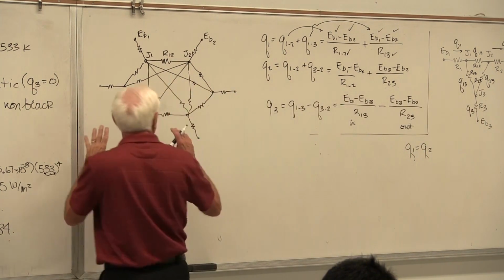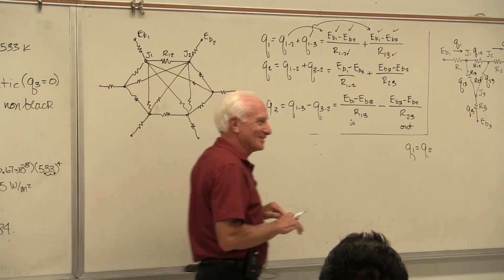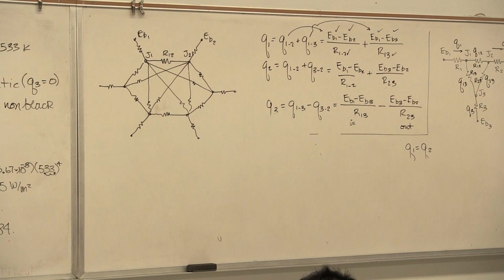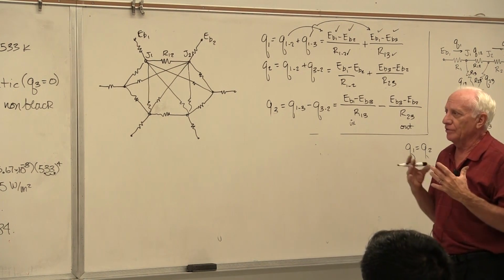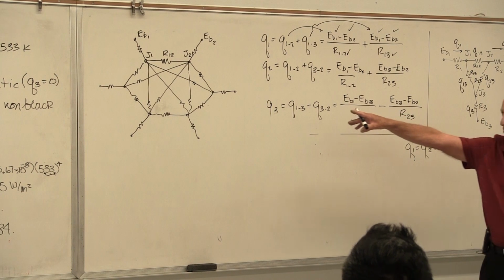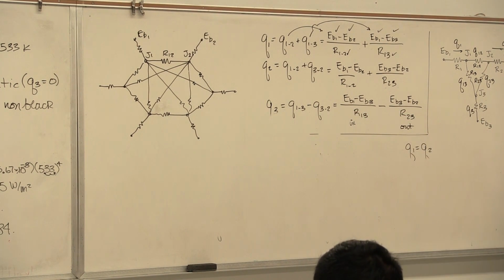Okay, so we don't use these circuits for any more than 3 surfaces. It's more to give you a visual graphic feel for the problem, if it helps you that way. Sometimes it helps people to see for 3 surfaces how the heat might be flowing. But when you try and draw this for more, it's pretty much worthless to try and analyze it that way. Extremely difficult. So fall back on the equations.